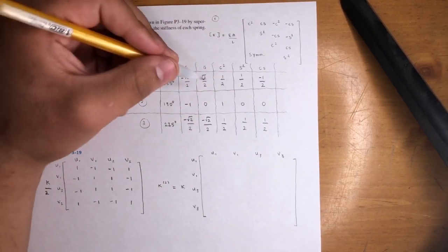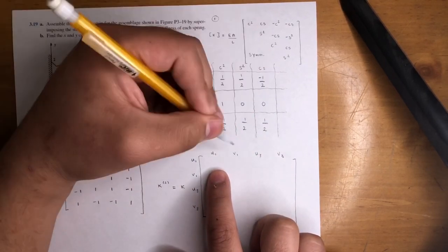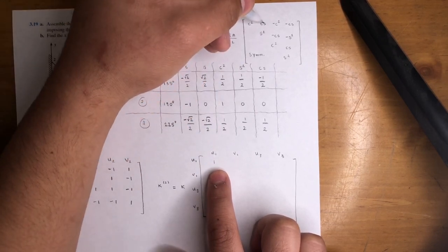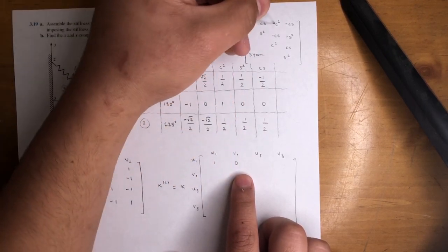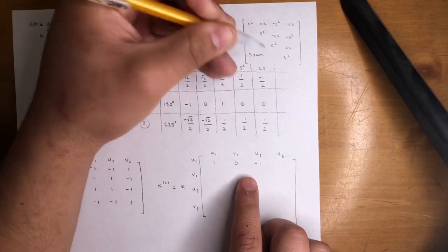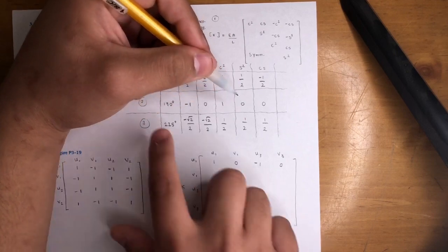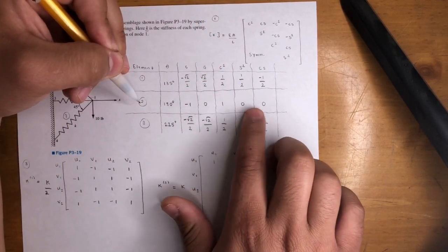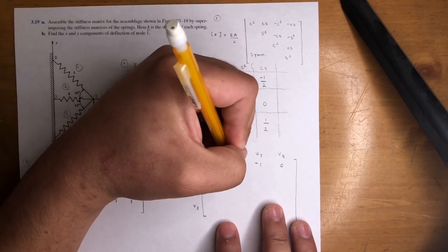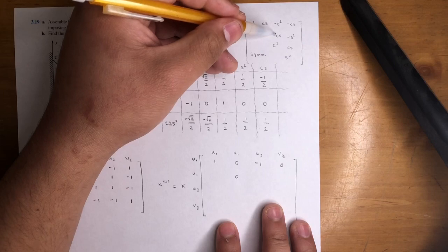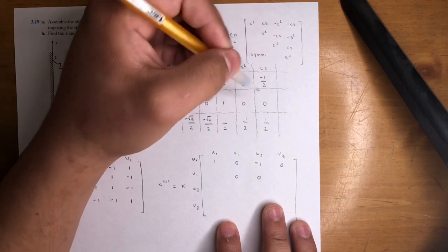So for element 2, we've got C squared right here, so it's going to start here. C squared, that's going to be 1. CS is going to be 0, okay? Negative C squared, it's -1, and then negative CS is just 0. Next one, S squared, for again element 2. I'm looking at element 2 now, so 1, 0, 0. That's all I'm looking at. So it's S squared, which is 0. It's negative CS, which is 0. And then it is negative S squared, which is 0.